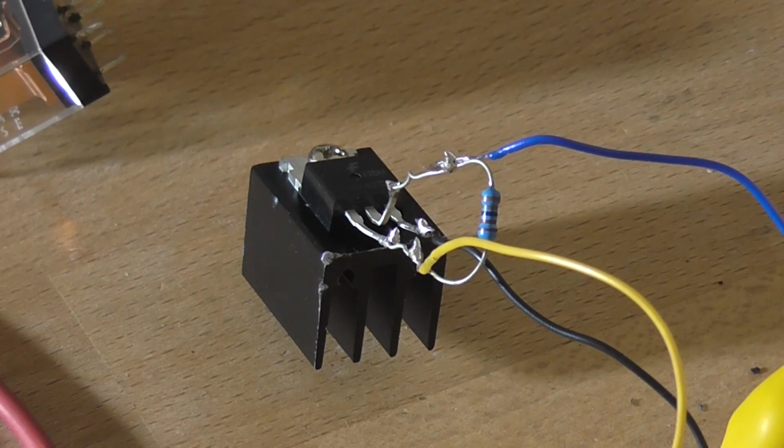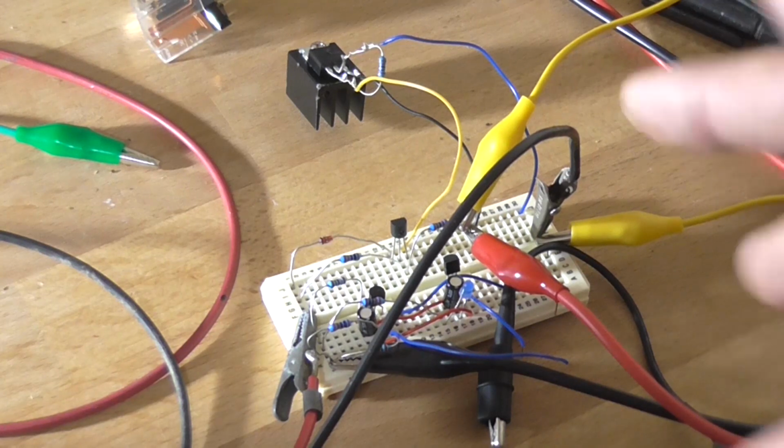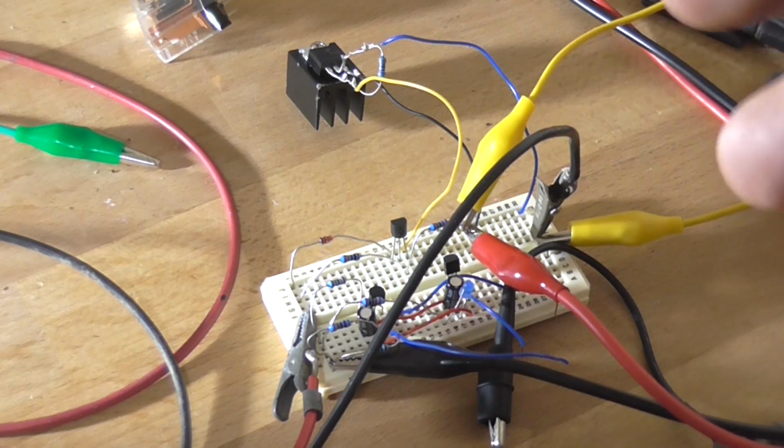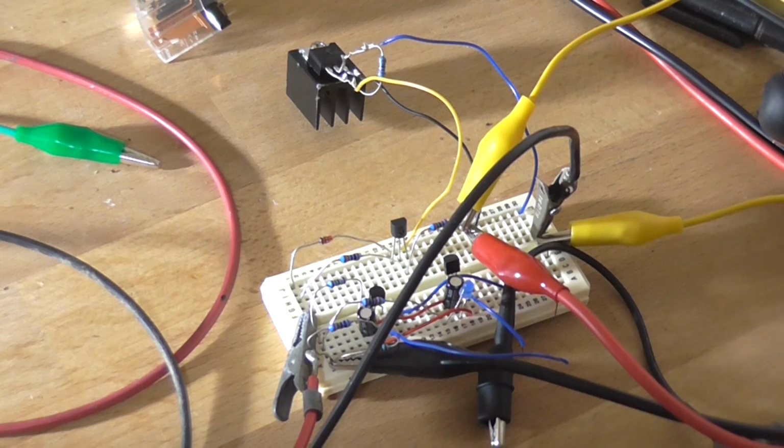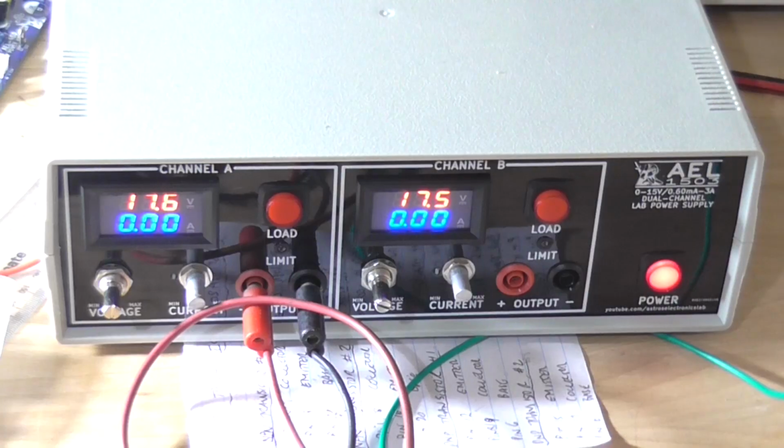That means that the resistor value is too high for the supply voltage now, so well, I could change it, but in the end this circuit is going to be used in an amplifier power supply to give me a plus minus 15 volt rail off of the plus 35, minus 35, or plus 40, minus 40 supply rail, whatever it is. So what I'll do is, as I've got the other channel already set up to mimic a total supply voltage of minus 35 volt in this case, I'll just connect the two supplies in series.